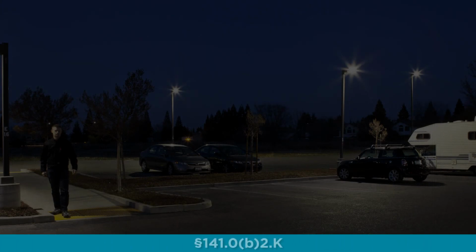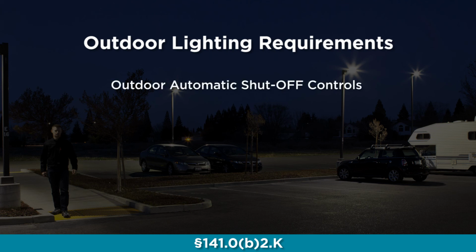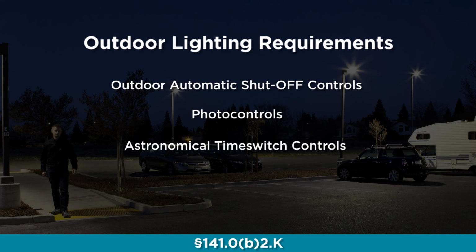In the 2016 code, there is a change in procedures for outdoor lighting control acceptance test. Outdoor lighting controls and equipment previously had a limited set of functional tests as part of the acceptance test process. Now, all types of outdoor controls must undergo functional testing in addition to inspection. Acceptance test requirements and procedures for many types of outdoor automatic shutoff controls have been clarified and/or expanded in the 2016 code. Specific functional tests for photo controls, astronomical time switch controls, and part night controls are now available.